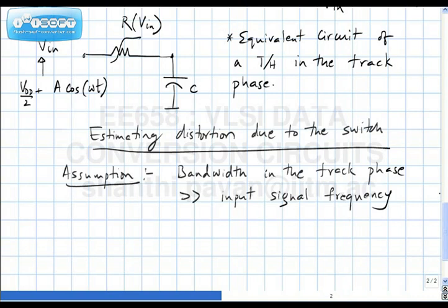There's some nonlinearity. Okay, so can you comment on what the distortion would be if omega was 0? There will be no distortion. Why? At DC there is no distortion in spite of the resistor being nonlinear. When I say DC there's no distortion, I mean the DC is within quotes, it's not a sinusoid, right?